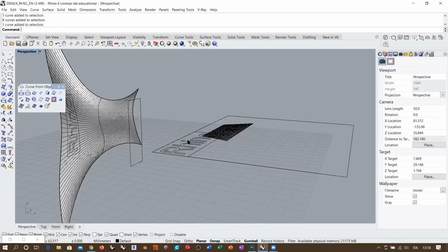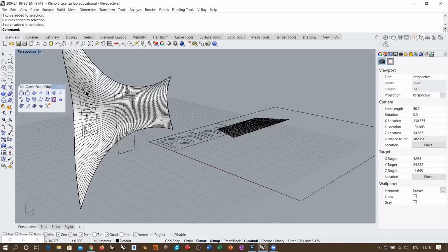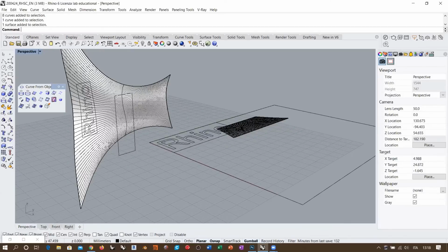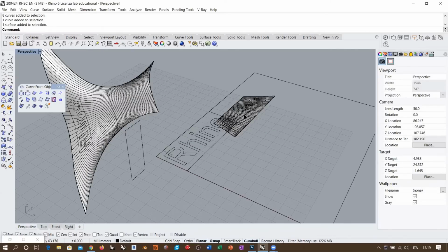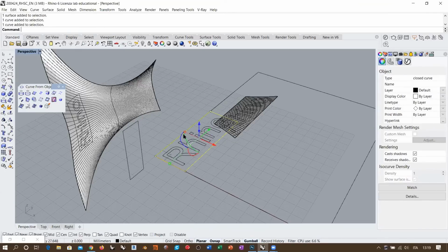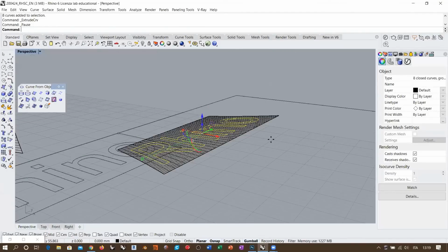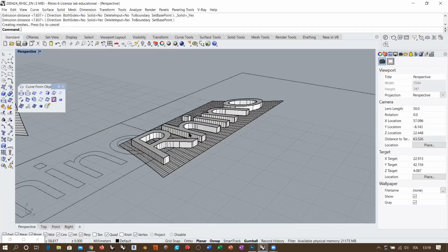So for example, in this case, if I wanted to apply a three-dimensional text on this surface with this regular behavior like this, I would apply a UV curve to determine this area, and then apply a UV curve to determine this area, and then apply a UV curve to get to this text right here. And then I will take this text, extrude it solid like this, in order to give some thickness to the text.